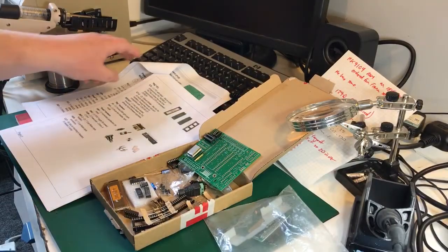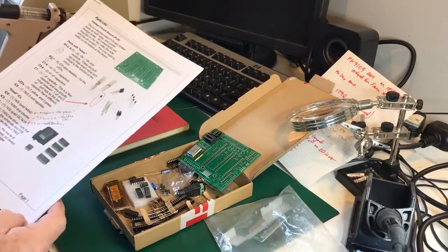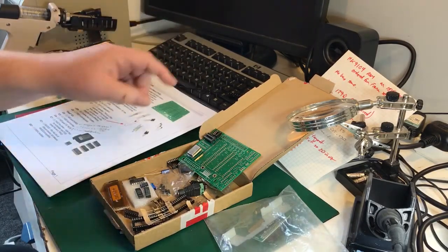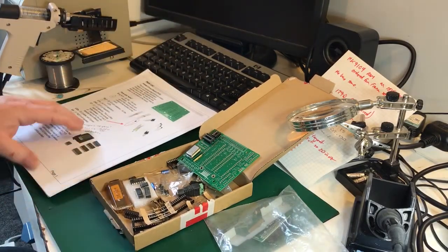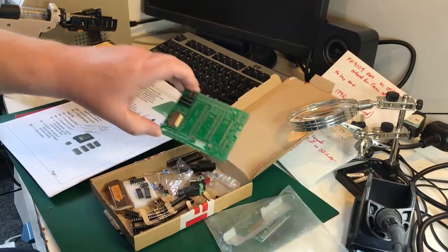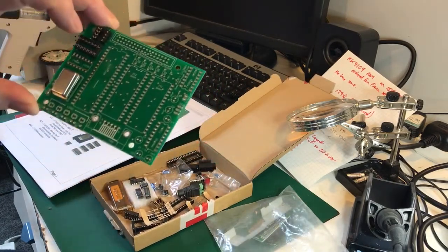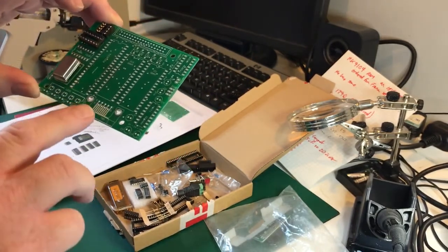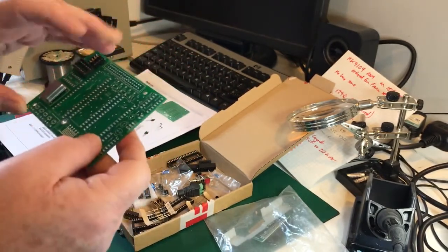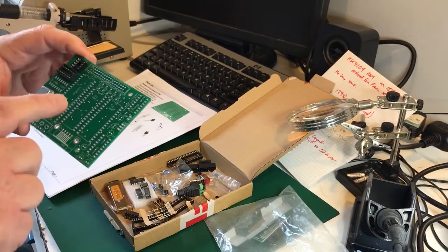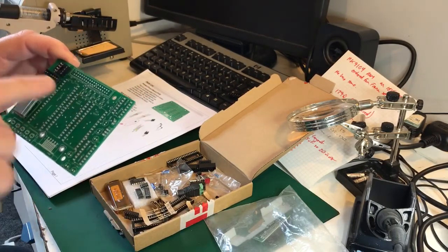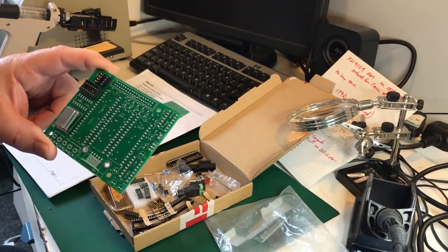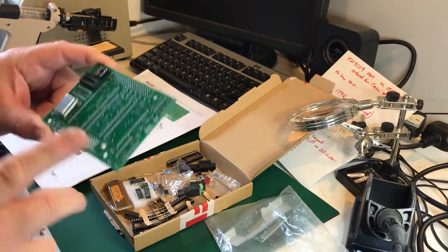So today I'm going to build the virtual disk, the SVD. Which is basically a PIC-based emulation of a disk drive, which can do hard-sectored emulation in RAM. So if you've got an RS-232 connection, which transmits a couple of disk images into the RAM chips, and the PIC then simulates the output of the machine. It becomes a floppy drive, effectively, with some LEDs.